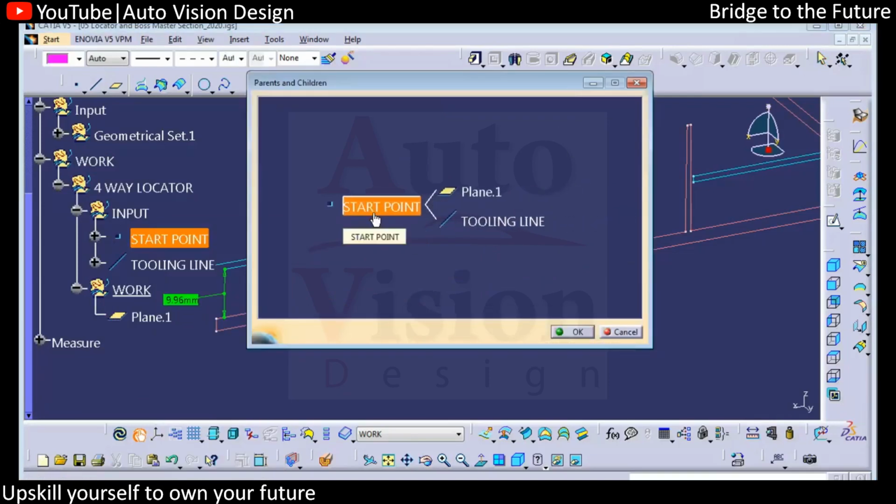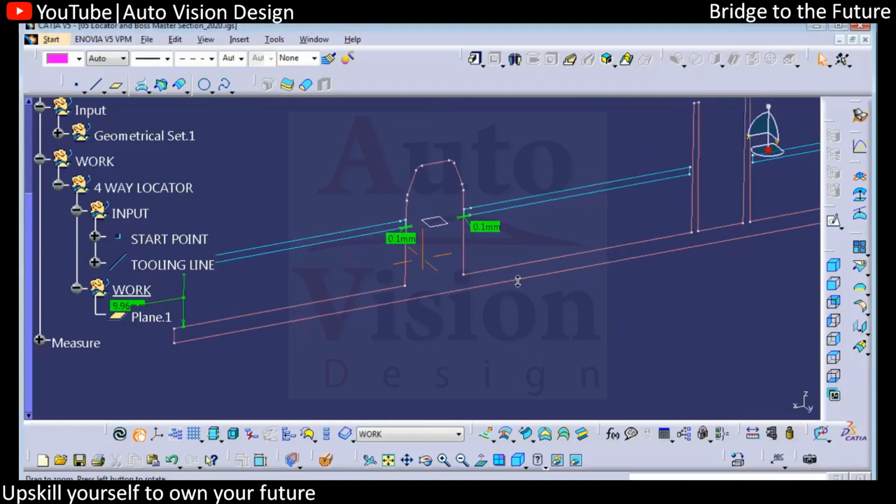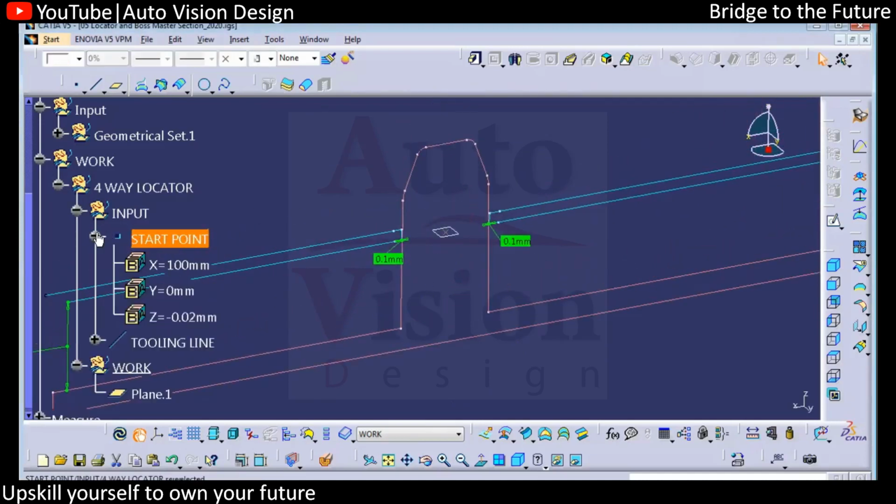We used this point to create first with a reference to the given input. But now we don't want that input, as this is not preferable. In CAD test also you should make sure this point is not linked with any master section or given input. This is a bad impression. So always make sure you have a point which is fresh, in a different coordinate. Then the tool maker or the CAD test creator can change this point.